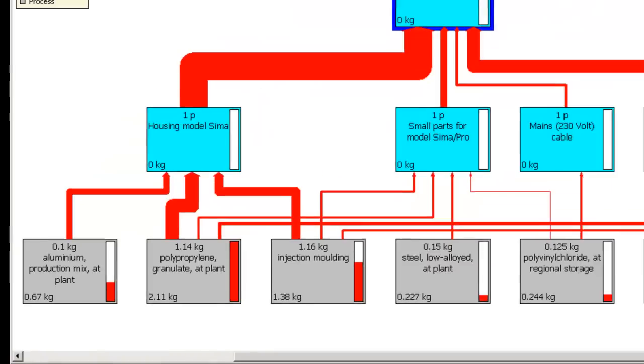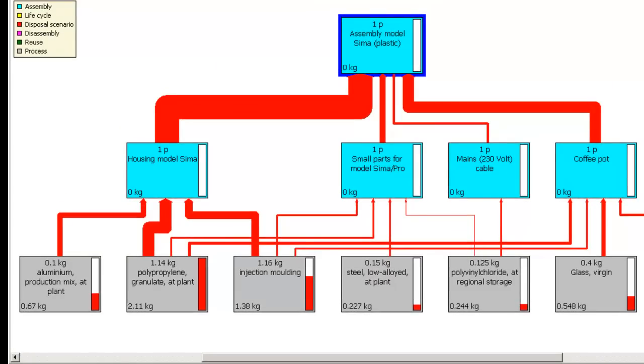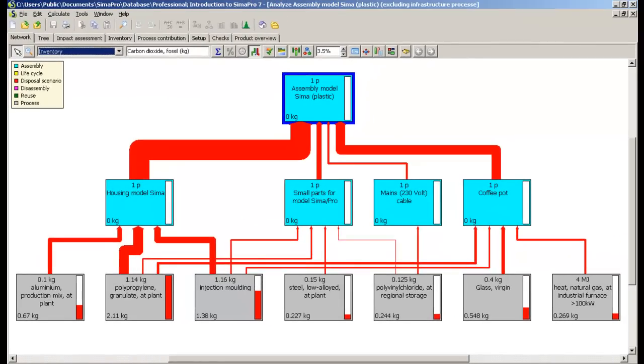You may notice that the assembly and subassembly nodes show the indicator as being 0. This is because when you create your model in SimaPro, emissions to air are entered at the process level. So far, we've explored only 2 of the possible 7 indicator options. Using other indicators, you can take a closer look at a specific damage or impact category, or the flow of a single product. Try to take time to experiment with all the different indicators.